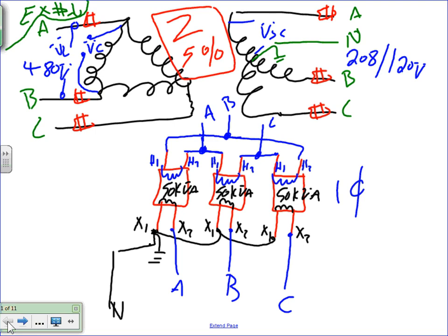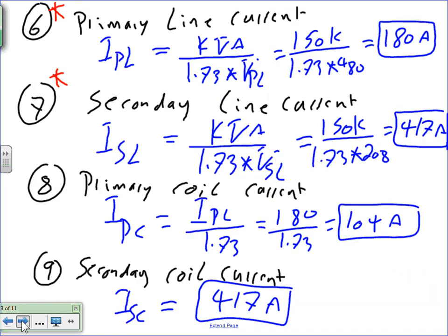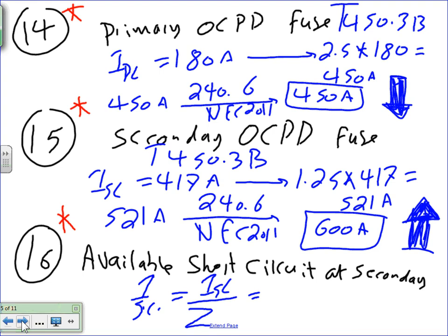The only restriction on how much current can go into your building is the valve, aka the transformer, that's holding that current from burning your building. The valve is activated by the impedance. The impedance of the transformer acts as a valve that protects the building, chokes the current, and does not allow all the current to go through. That makes a lot of sense when we start doing short circuit analysis. So the available short circuit is based on an unlimited amount of current coming into the transformer primary.